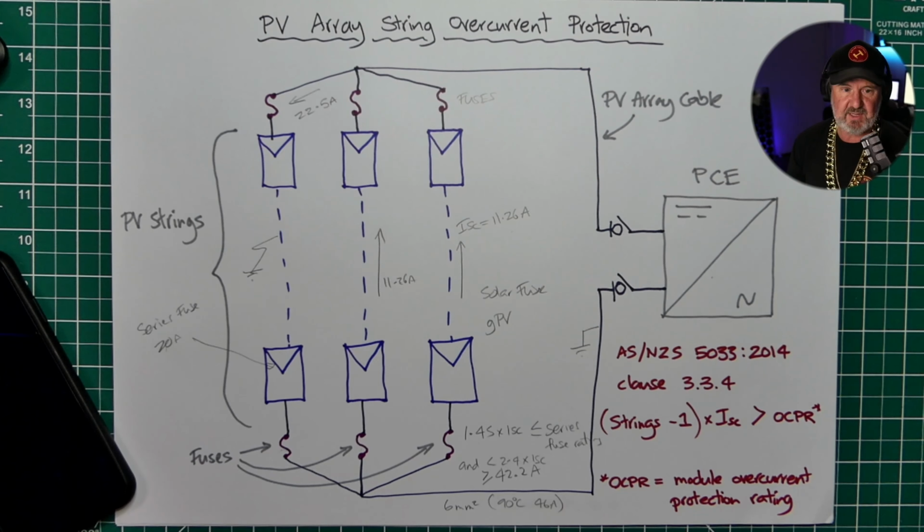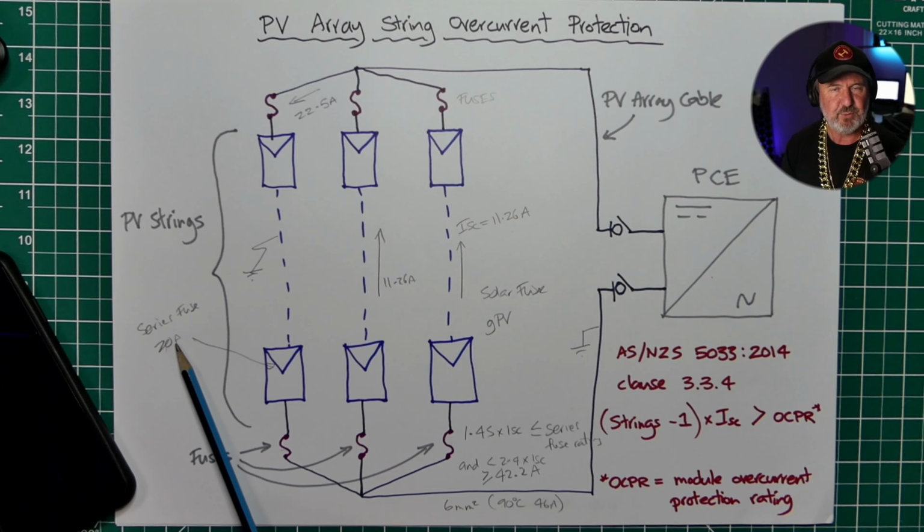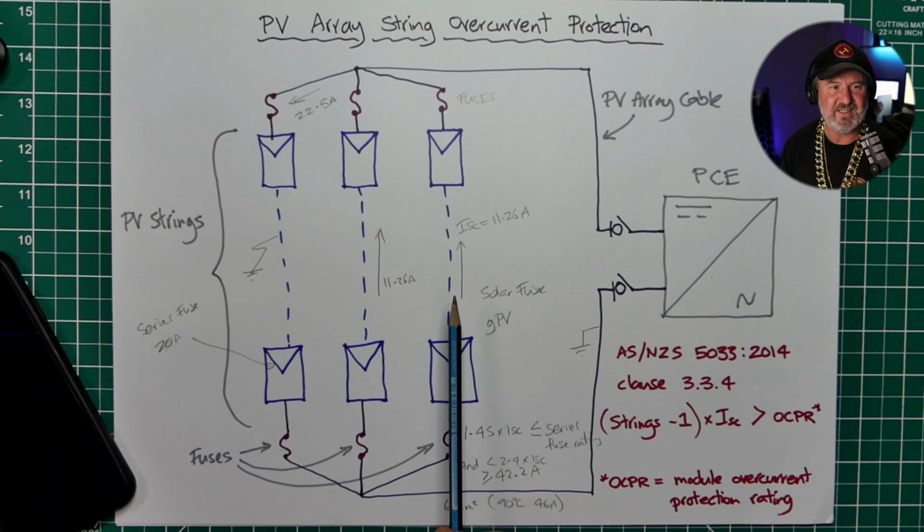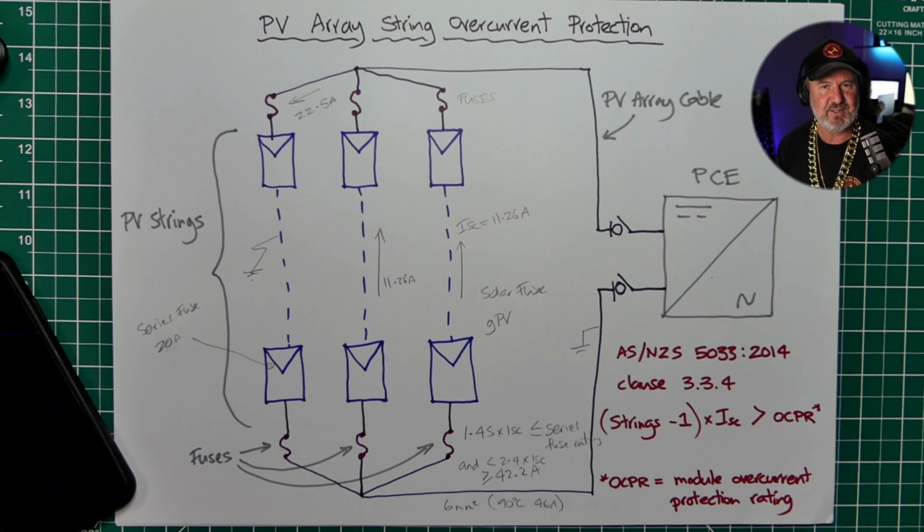So just coming back to that range, my recommendation, by the way, is always use the maximum. Always try and go to that fuse rating that the manufacturer specifies. The reason for that is you just don't want false tripping in a multi-string system, and this is because you just don't know it's happened. If you've got 3 strings and you lose one, the customer probably will never know. In fact, embarrassingly, this has happened to me.